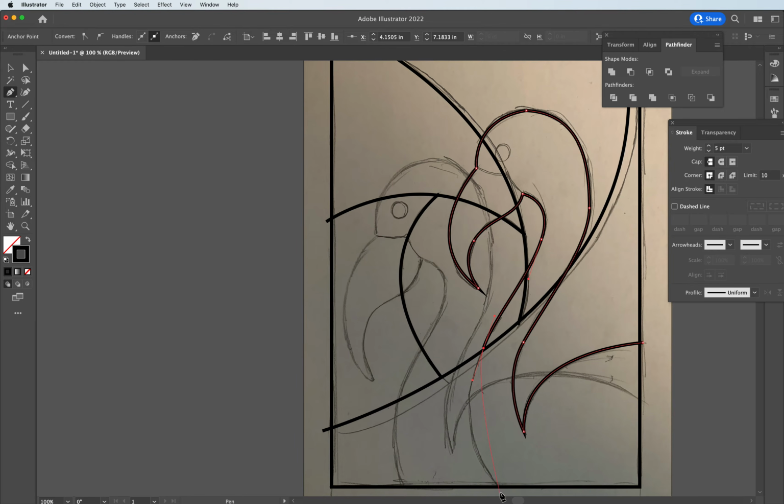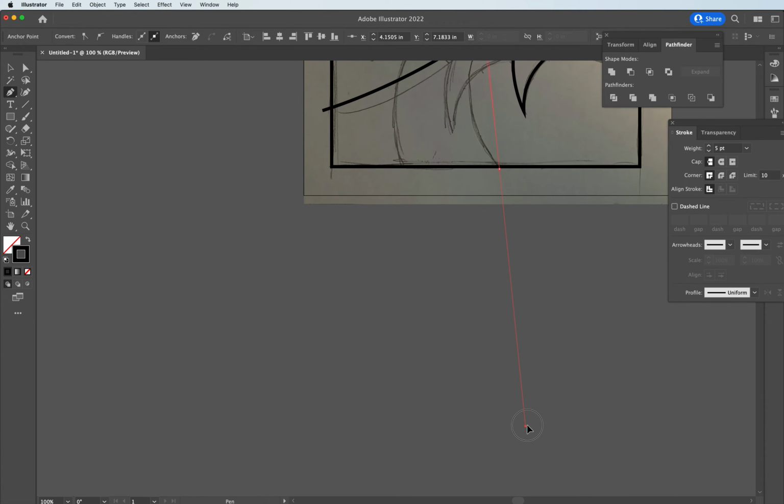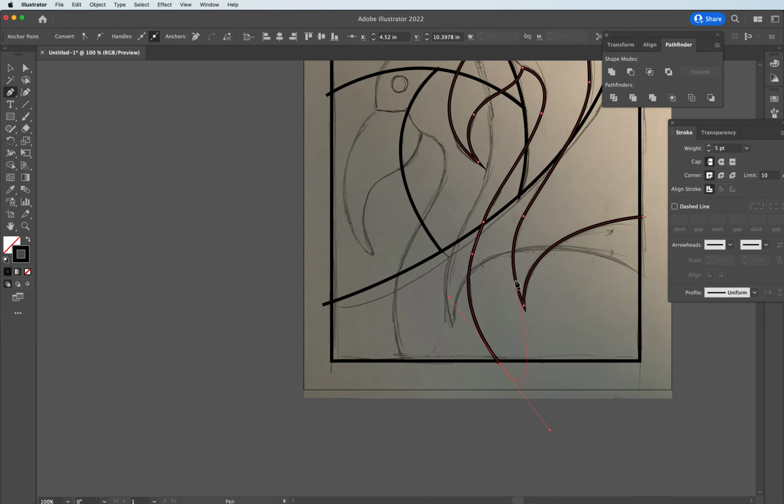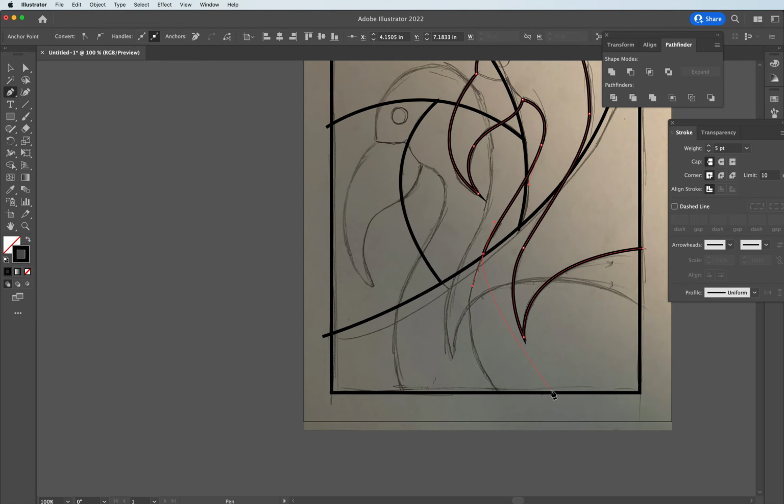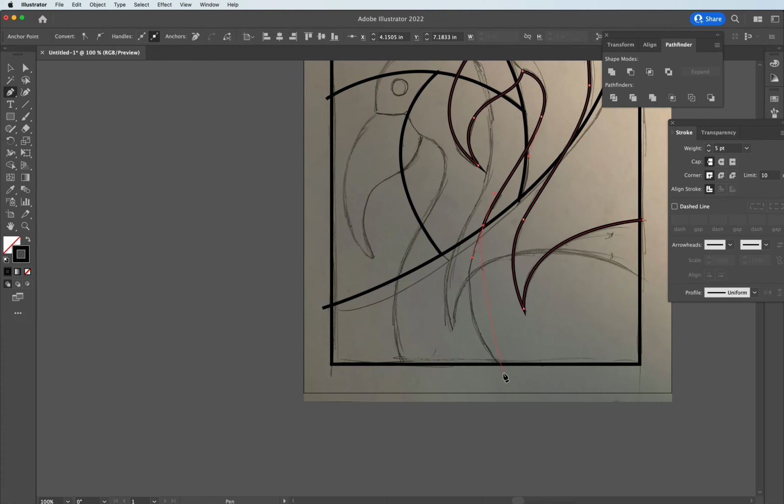And click and drag to create the bend, and then overlapping again to match the bend on the body. So again, if I'm not satisfied with the curve, I can always hit Control Z to undo. So I'm going to zoom down a little bit. And even if I do go past the shape, I can always eliminate these extended lines later on.